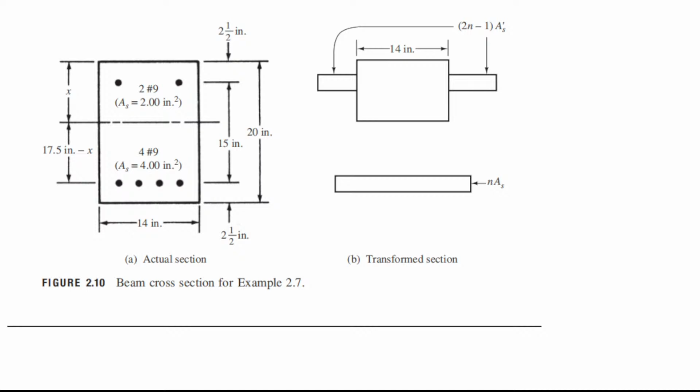And we have the concrete cover, 2.5 inches. From this point, the extreme fiber, up to the center of the reinforcement, is 2.5 inches; that is the concrete cover.